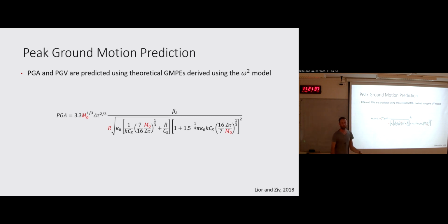The end user of an early warning system, basically all of us, we don't care about the magnitude, we don't care about the location of the earthquake. We only care about ground shaking intensity at our location, whether we need to take precautionary measures or we can keep doing what we're doing because the earthquake is not going to affect us. So this is the end game. This is what really matters: the ability to predict peak ground accelerations at a specific site. And early warning systems use these types of equations to determine where and if an early warning should be issued.